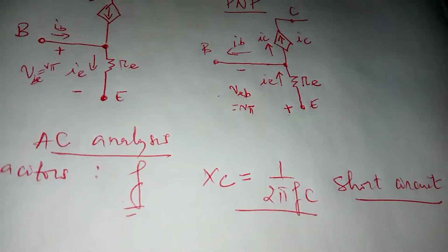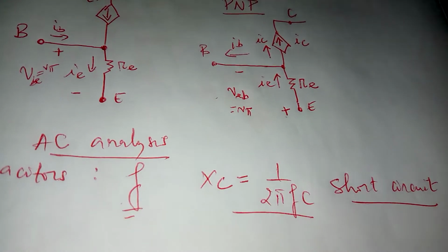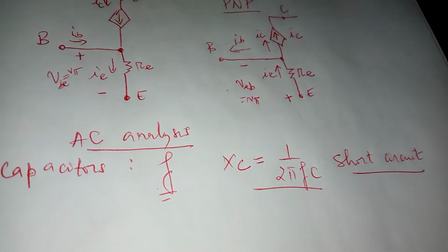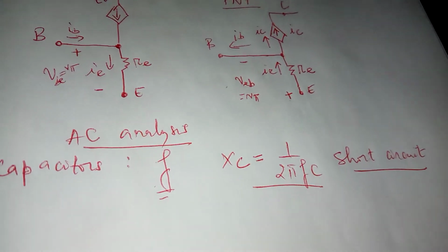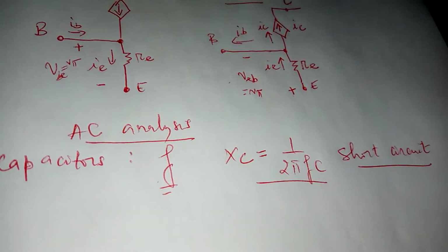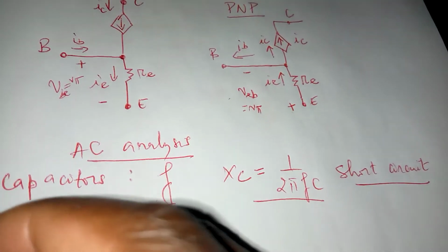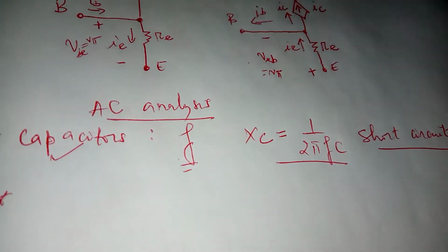Although we're going to go into more detail in Electronics 3 in terms of the impact of capacitors on the design of the amplifier, for Electronics 2, capacitors, while doing AC analysis, behave like short circuits. Very important, and very important to apply.